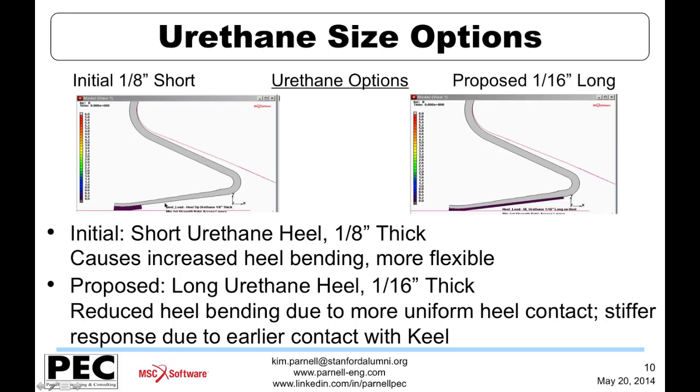And I'm utilizing the solid shell elements in Marc in this model that allow you to specify layers of material. They can also be defined on a per layer basis, but you can define groups or layups of material of specific orientation and thickness.